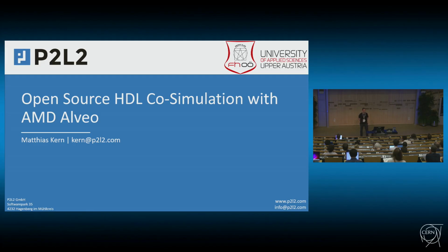Thank you for the interesting presentation. Just one simple question. I did not understand: the clock is generated by the simulator, like the co-simulator? The clock, so you don't want a generated clock in the FPGA. So there's just a clock gate in between to only run a single clock cycle when there is new data, to keep the device synchronized with how it would have been in the simulation.